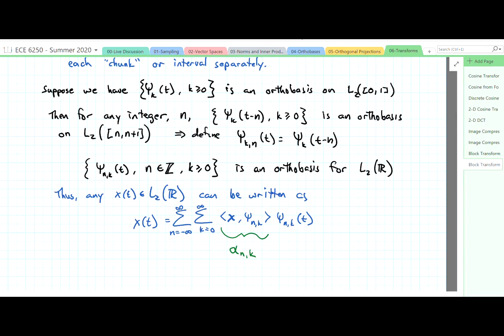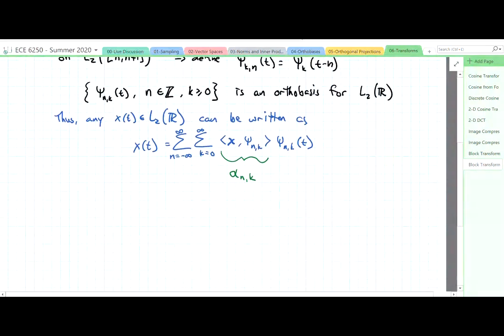So, using this handy tool, now we can look at doing some analysis of the signal for all time. If you've had any signal processing courses before, you've seen something like this already. The short time Fourier transform is what we use to get spectrograms, for example. It effectively divides a signal up into blocks, takes the Fourier transform of each block, and then if you want the spectrogram, you can plot the magnitude of those transforms at each instant of time, and you get an image.